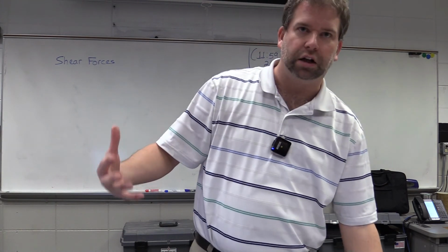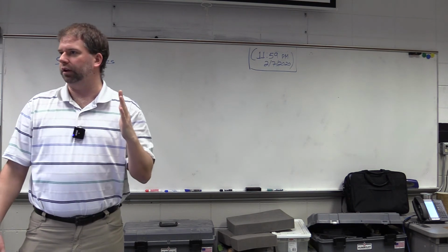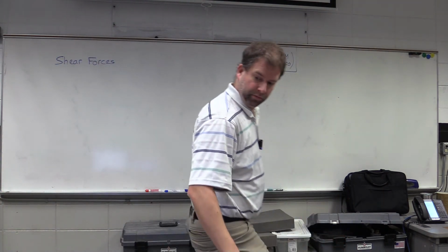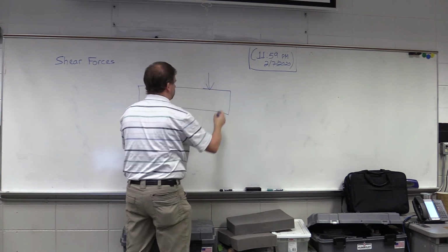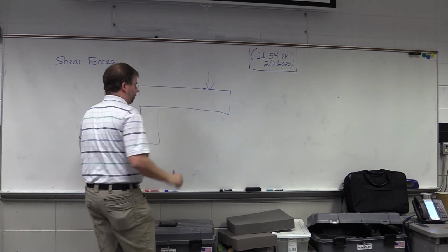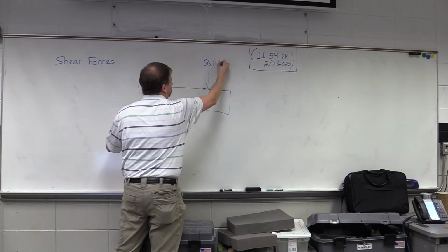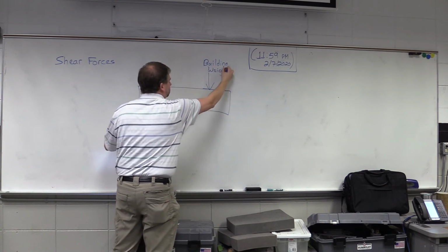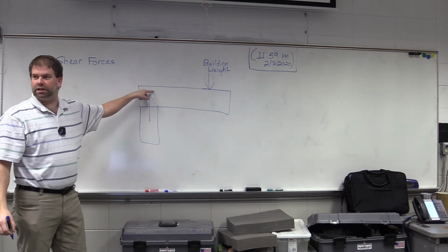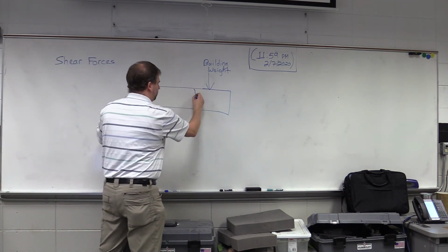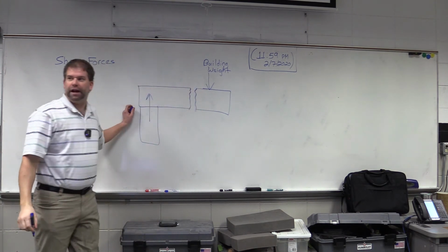So if you think about a steel beam, a concrete beam, we get a nice, well, not necessarily always nice, right? But a straight-ish fracture through the material itself when we see shear. And what's happening is, if we have a concrete beam here, and some sort of concrete column over here as well, right? This is a force applied by the building, say building weight. And the column is providing resistance, okay? If we don't size this thing appropriately, we could end up getting a break in that concrete column, where the thing ends up fracturing, okay, and shearing off.